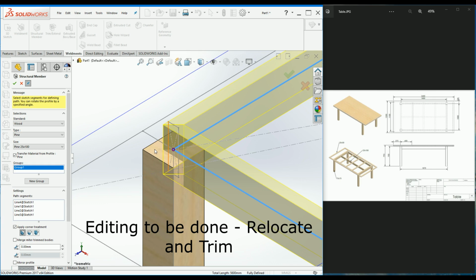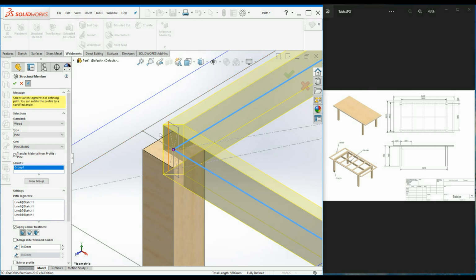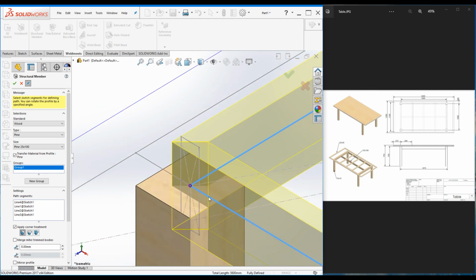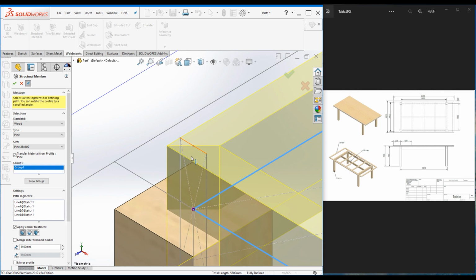In order to do that, we have to select the profile pierce point for the profile. By default, the pierce point is the origin of the sketch, that when you create your profile, but you have the capability of adding further piercing point at the time of you are creating the profile. So now I have added one at the top center, so we can select this point.